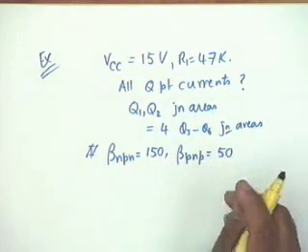You might ask me, they are identical transistors made on the same chip, how come beta PNP is less than beta NPN? This is also a fact of life, and that is why NPN transistors are preferred over PNP transistors. To get a high beta with a PNP transistor, one has to spend much more than one does in an NPN transistor.